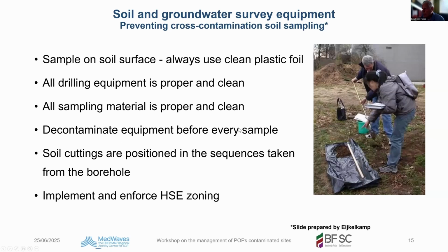Decontaminate equipment before every sample. So you clean your equipment between every sample. The cuttings, this one here, are positioned in the sequence taken from the borehole. So don't mix them, but use a certain sequence to put the borehole cuttings. And implement and enforce health and safety environment zoning. And I'll come to that.